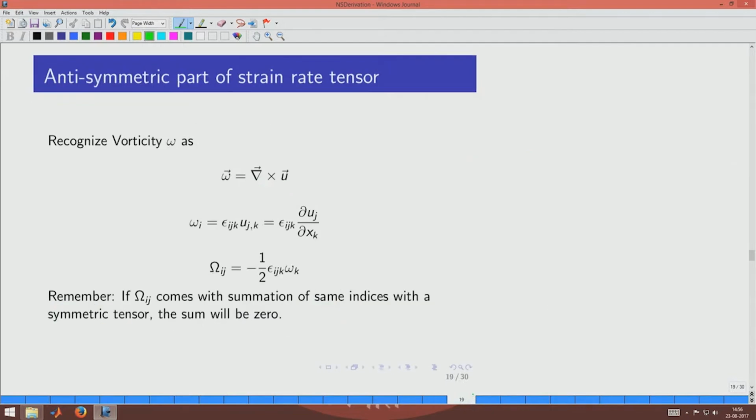So, once you do that, we also can see how the rotation part can be related to something else. We see that the rotation part can be related to the vorticity, which we introduced as part of the planar flows session. So, you could see that the vorticity is related to the omega in this manner. Okay. And because you have got only 3 different components in omega, because it is an antisymmetric tensor, those 3 can be the components of the small omega, capital omega and small omega being related.